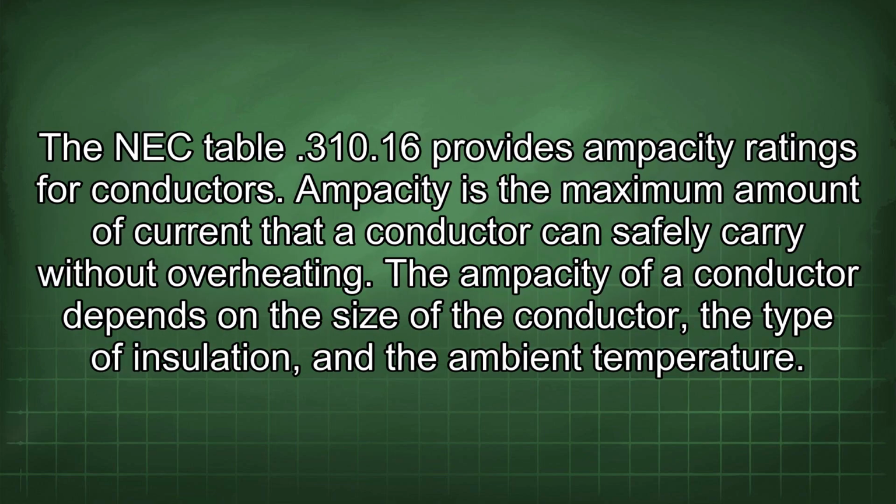The NEC table 310.16 provides ampacity ratings for conductors. Ampacity is the maximum amount of current that a conductor can safely carry without overheating. The ampacity of a conductor depends on the size of the conductor, the type of insulation, and the ambient temperature.